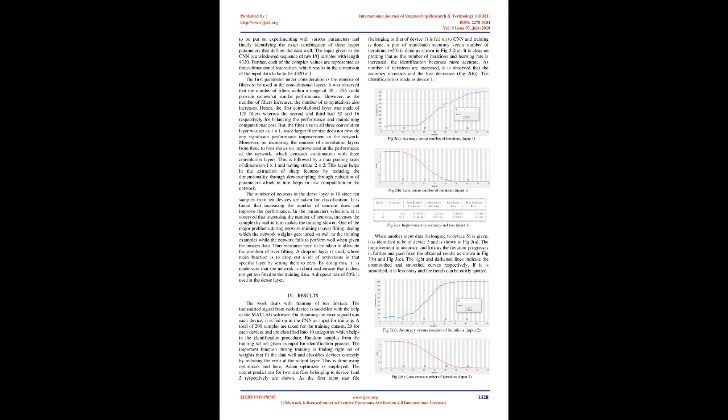A. Data generation. The sequence of binary data samples is generated based on a particular number of samples for each device, then modulated with the help of quadrature amplitude modulation, QAM. After the modulation, the signal is converted to orthogonal frequency division multiplexing, OFDM, data by taking the inverse fast Fourier transform. These OFDM signals are generated for a specific range of signal to noise ratio, with 64 FFT size and 52 subcarriers, and a pilot is added before conversion of OFDM modulation. Similarly, we generate the input for all devices, save it in a .mat file and load it for testing. B. Convolutional neural network.